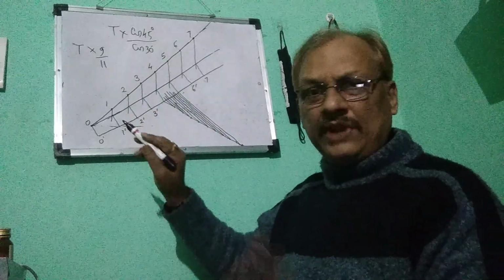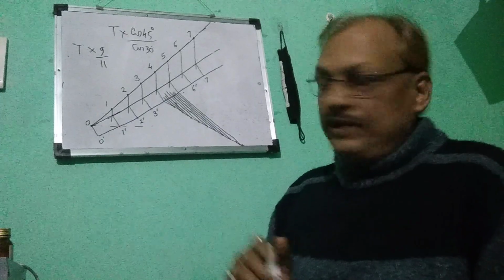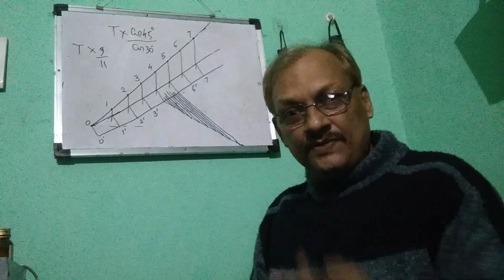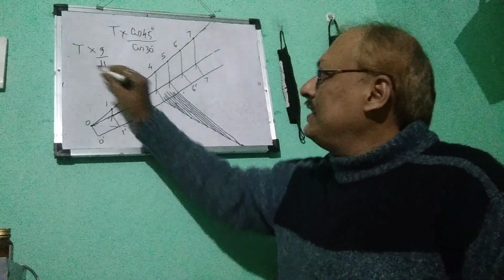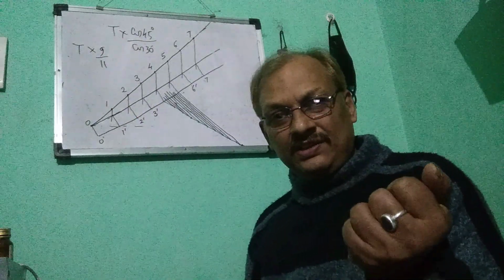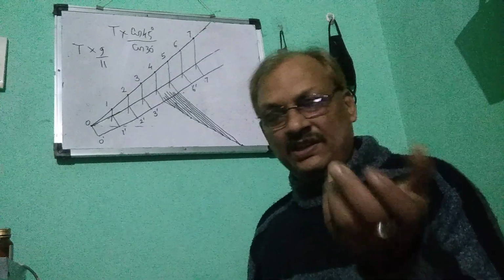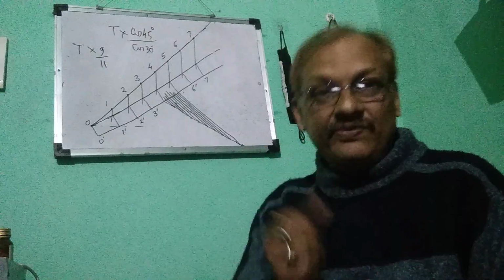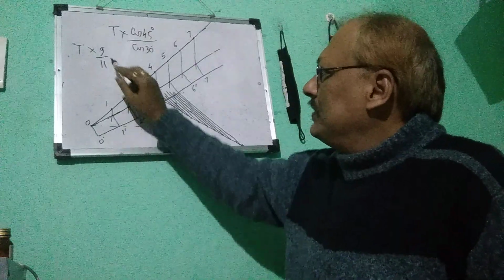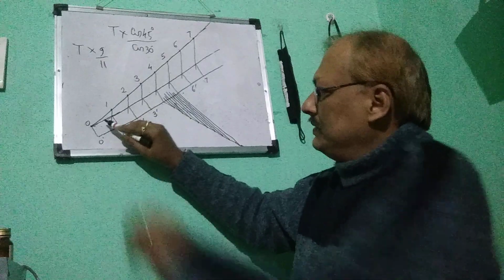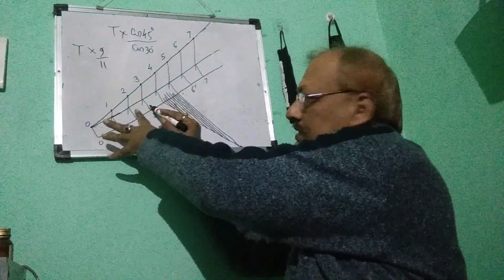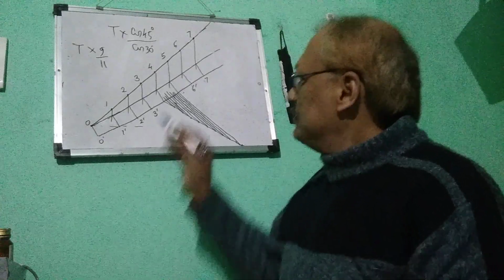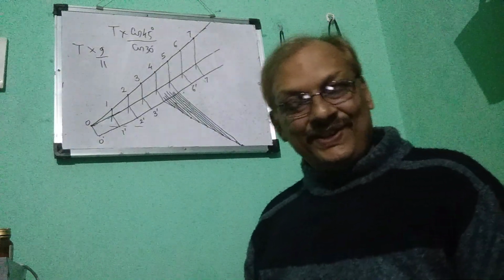So you don't have to calculate anything. I will not recommend you to calculate each and every length, because so many lengths are there, and in helping diagrams also so many lengths would arise. Every time if you calculate, you will not get a nice, correct figure, and the errors will be large. So just see from that same scale how much 30 is. It may be 28.5 or 28.2 like that. So that you make in your final drawing. Okay. Thank you.